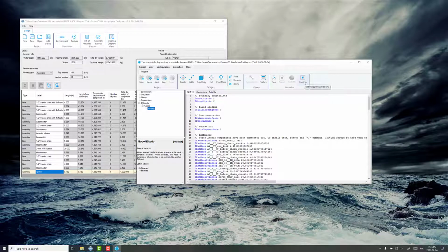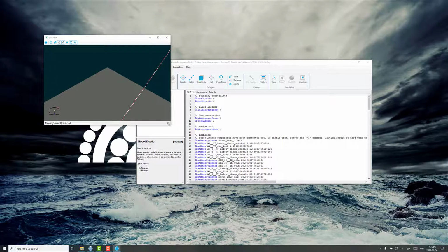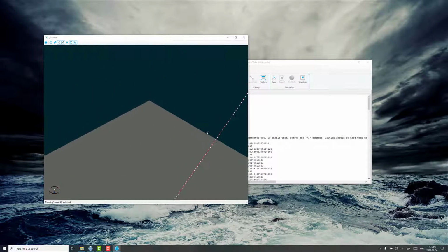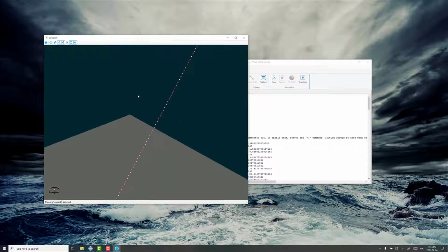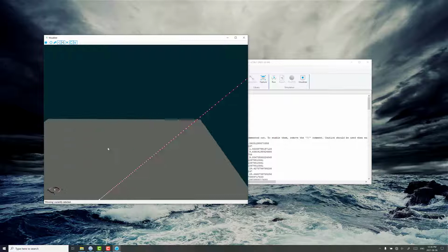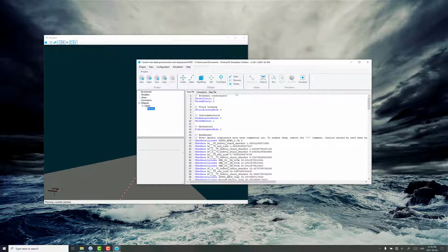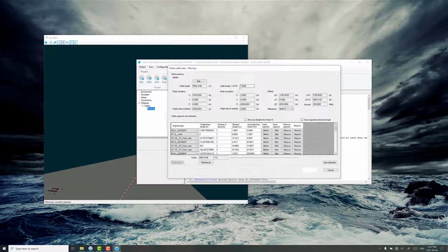So if we look at the Previsualizer for this, I'll just close this here. The Previsualizer's got some arbitrary profile right now. We haven't solved for the static profile for this mooring in the current profile, so it's just starting with a diagonal line. For an anchor last deployment, we want it to be lying flat along the water surface. So make sure we've got mooring selected here in the tree, click on state, and we want to edit the geometry profile for the cable.